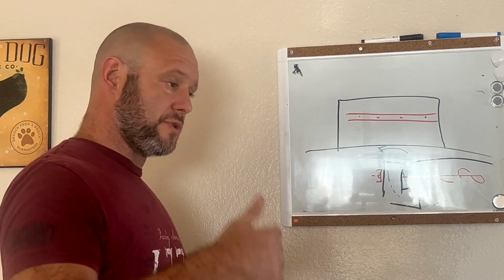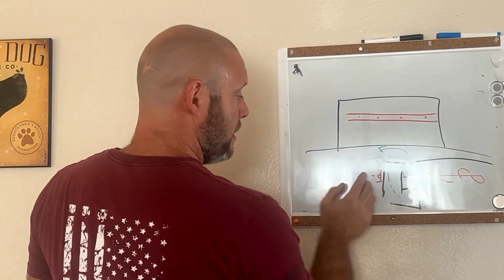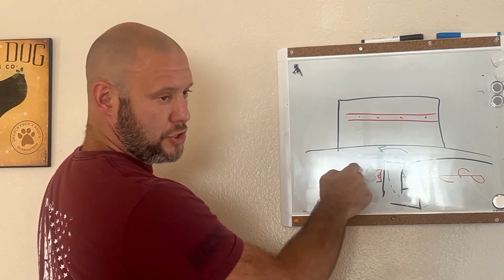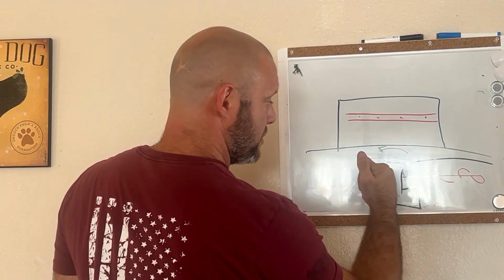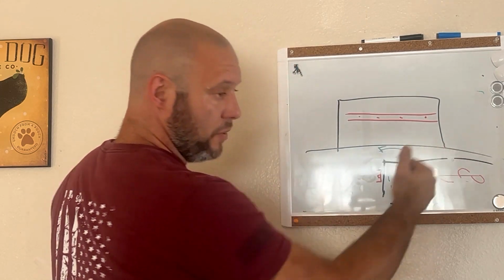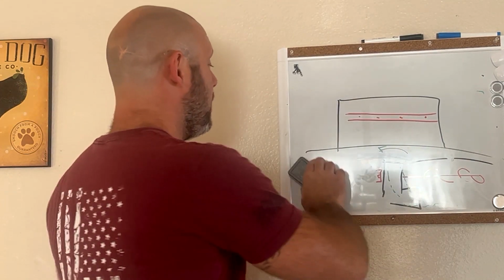If it's soil nails or tieback anchors, or the wall plates with the tieback anchors to help pull on this I-beam. I'm showing an I-beam, but it's a wall plate, right? And they anchor that in, which pulls in this direction, which can help straighten this retaining wall, right? Very, very good repair if we do something like that.